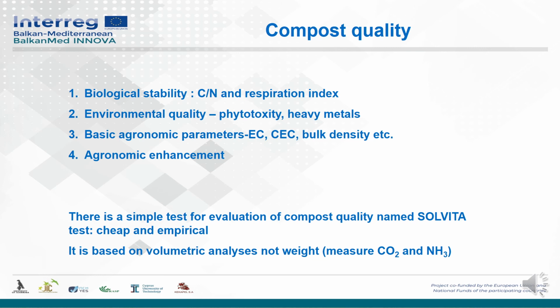There is a simple test for evaluation of compost quality, and it is really very simple. It is called the Solvita test. It is cheap and it is empirical. It is based on a volumetric analysis and is non-waste. It measures CO2 and NH3 or ammonium.